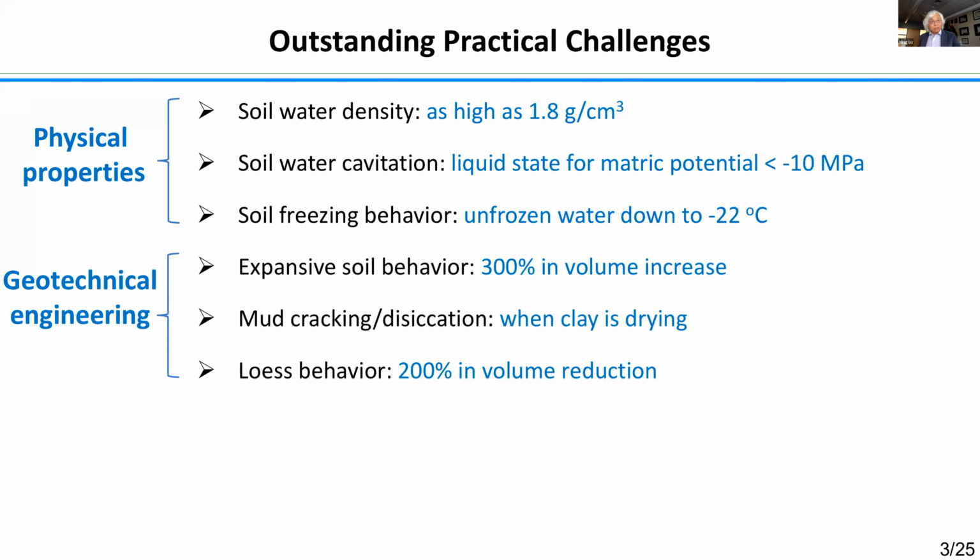Another area is geotechnical engineering. We deal with expansive soil, very widely spread anywhere. Expansive soil, what we sometimes call montmorillonite or 2-to-1 clay, is one of Mother Nature's final products before it goes back to subduction to be recycled from the weathering of rock. And the soil could expand its volume a few times upon wetting.